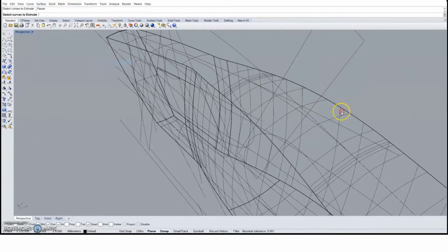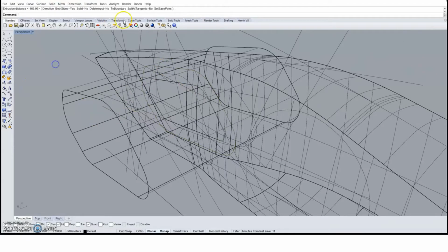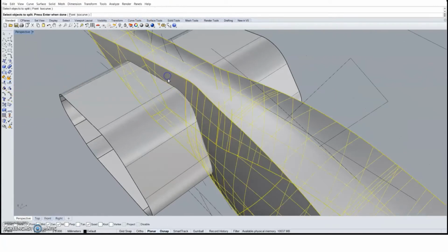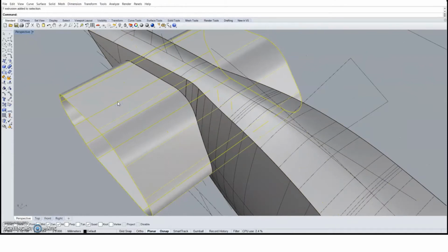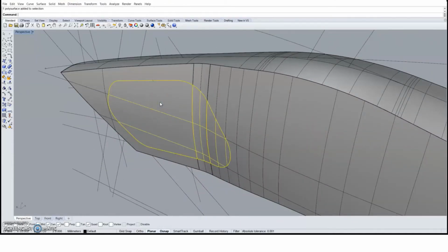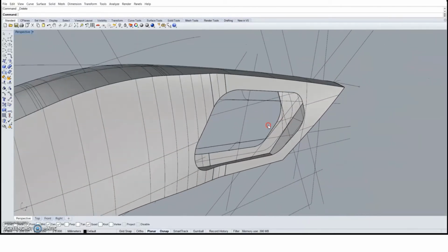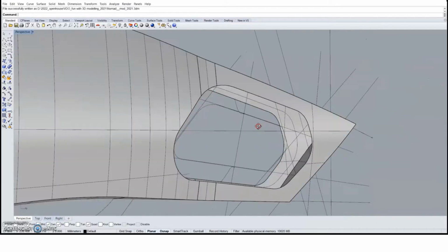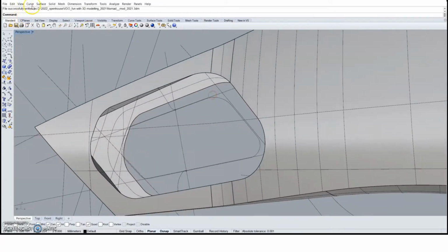And you can see also that as we start to create surfaces and curves, we are most of the time toggling between wireframe mode and shaded mode, so that it's easier to see and to work with. And now we have actually cut the two surfaces on both sides. And now you see that there's a hollow. So what we're going to do next is use those curves as a reference and create the internal surfaces of the handle.